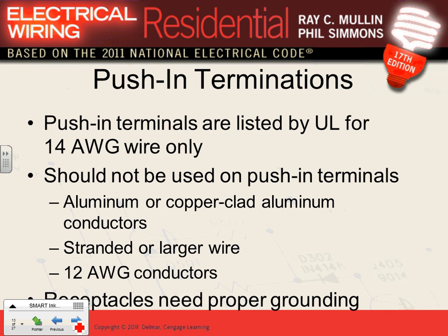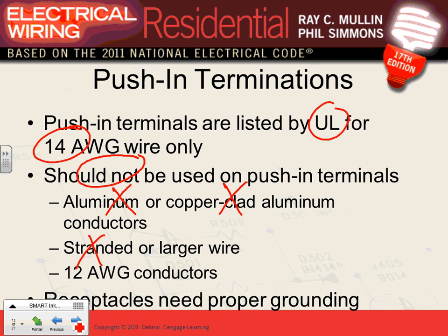We talked about push-in terminals at the end, guys. They're listed only for number 14 solid, not stranded. You cannot use them with aluminum or copper-clad aluminum conductors, and also no stranded. These push in the back, did you guys do them with us? You push it in the back in that little slot instead of terminating on the lugs. You can't use anything that's not solid number 14.